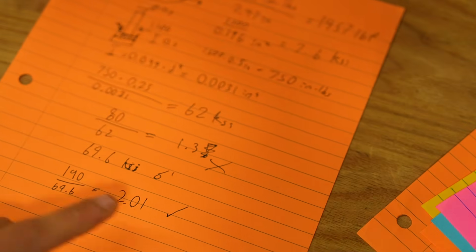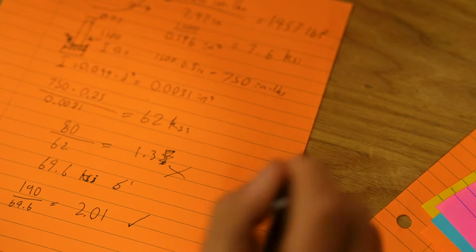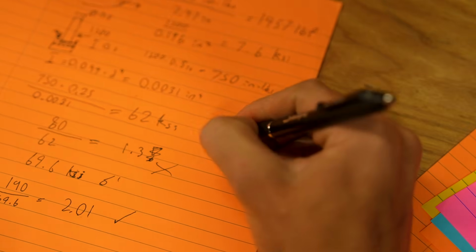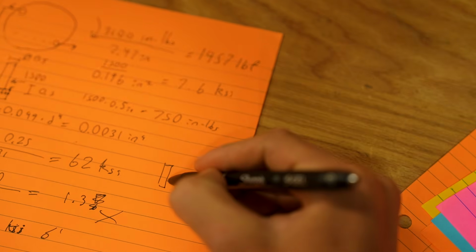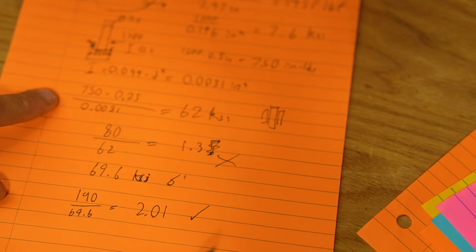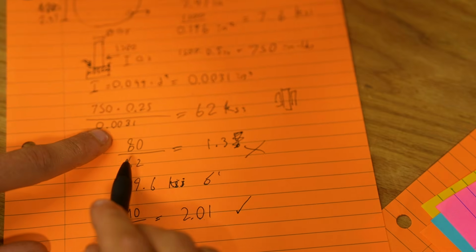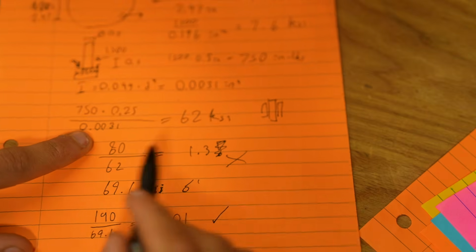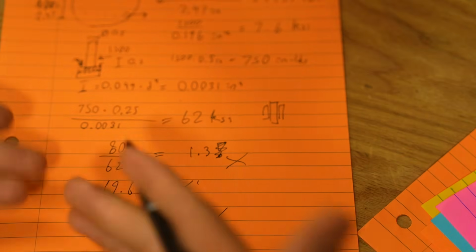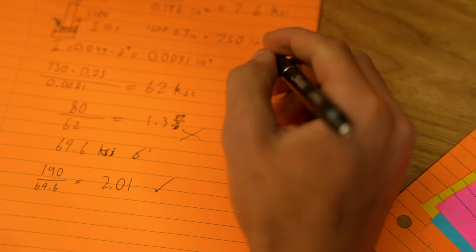So that's really close. The only reason I'm pretty comfortable with that is we made a very conservative assumption, which is not considering the sleeve around our bolt at all. A lot of this stress is driven by our really low I. The fact that I is 0.003 multiplies your force by like 300 times as compared to an I of 1.